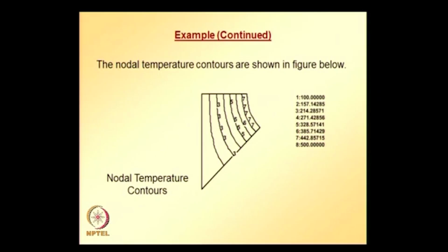If we compare these solutions with 8 elements, 32 elements and 72 elements, we can clearly see convergence of the solution both for temperature and heat flux values.